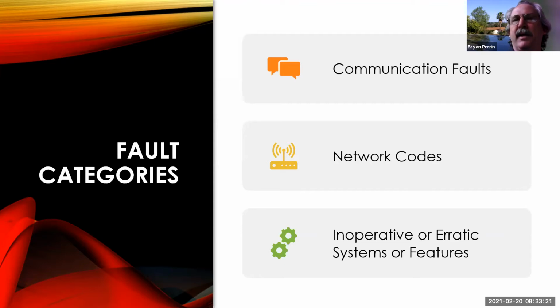Because of how we share information in vehicles today, if I get corrupted data, or don't get data, it's kind of a network problem because we're using the network. So is the network bad, or is it just not conveying the information? Or is there a module that should be working that's not?